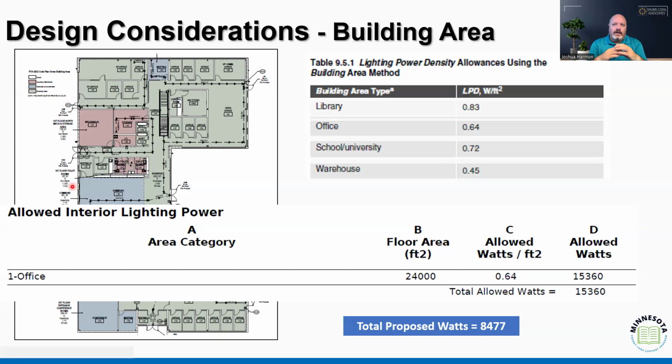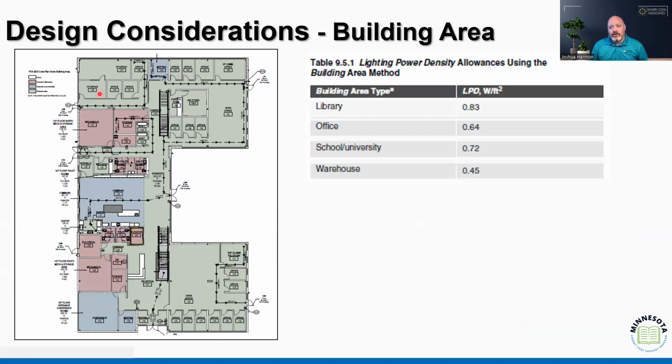And so again, there are calculations and determinations made at plan review. And then when you get out in the field, you need to verify as an inspector, is this an office? Or is this now a warehouse that has huge lighting capabilities and is not going to have but 3 occupants? There are certain calculations, and that's the way power and lighting really becomes part of the inspection and plan review process. So again, this one would pass, but the calculation for building area would allow you to differentiate all of these different spaces.